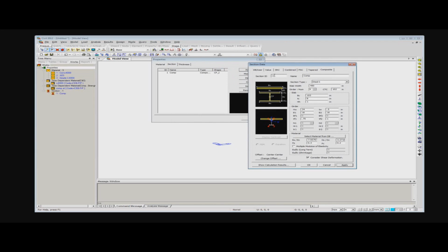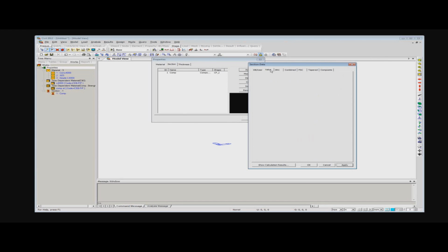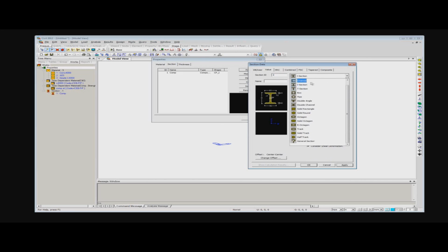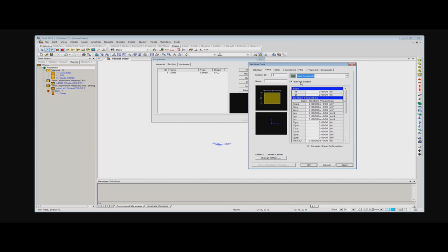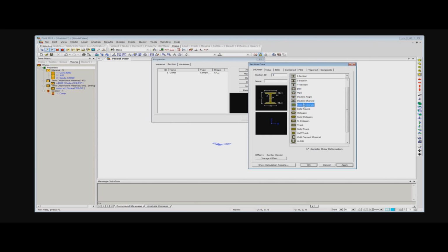The second one, I'm going to define the transverse sections. That's a rectangular section, so for that reason I'm just selecting a solid rectangular, or go to the user define and name it transverse section. Okay. With the user defined, h going to be 8 inches and the width going to be 36. Okay, down here you can see your section and apply.